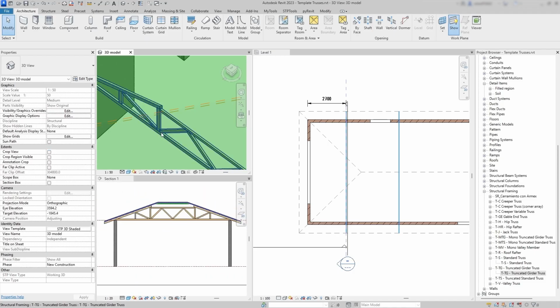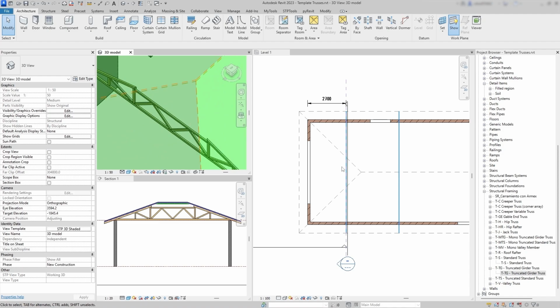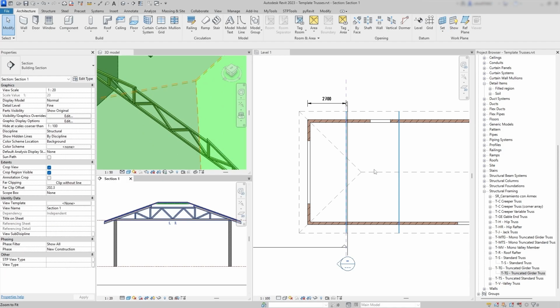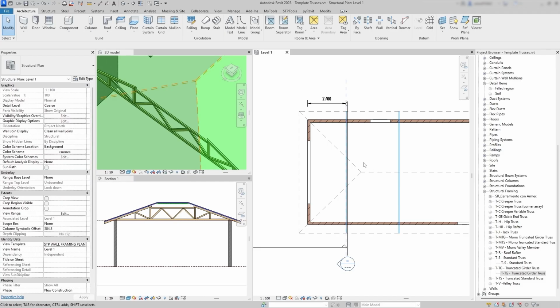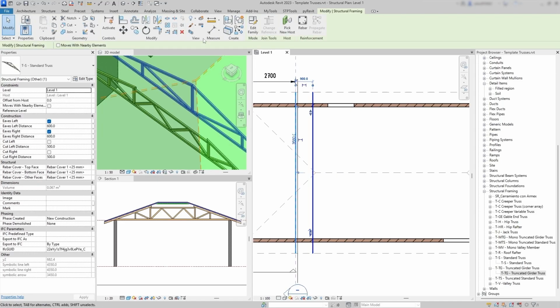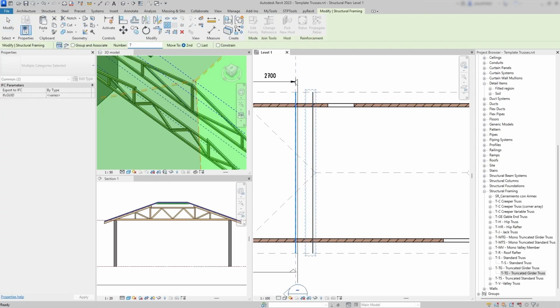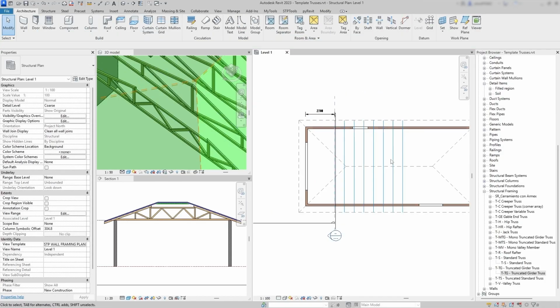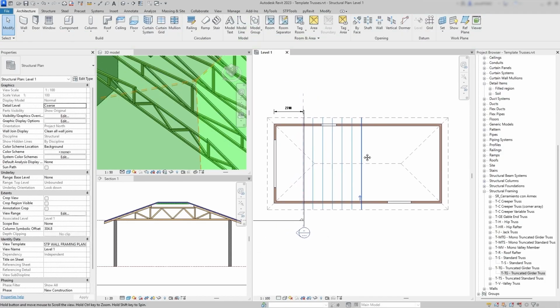Yep, just like this, and the truss adjusts itself automatically. We'll lock in the final support height later when the hip trusses are in their final spots. Alright, now let's space out our standard trusses from the girder truss. I'll speed through this part. Quick note, I'm only adding standard trusses halfway across the roof. The other side will just mirror later.